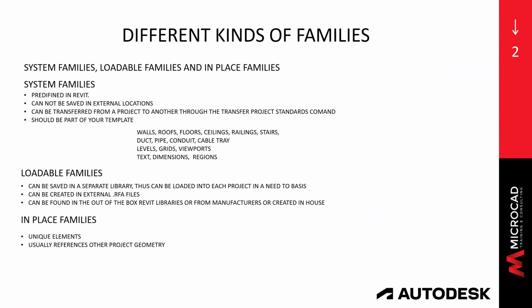The last type of family that is available is in-place families. They are families that are created within a project environment. They should be created only if you really need a project-specific family, and you need the actual project geometry of that project for that family to run.